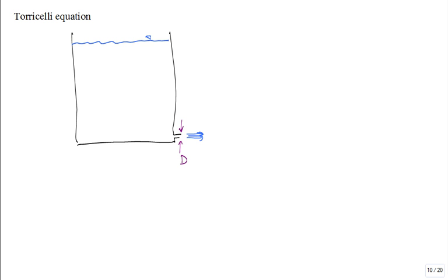somebody says, I think you can calculate the velocity of the fluid coming out of that hole. Can you please calculate the velocity of the fluid exiting that hole? Okay, what I'll do is I'll start right here, and I'll go with a line. That line represents a streamline. If I wait long enough, the fluid packet that started here would slowly go, and finally go out. And so along that line, I have state 1 to start it and state 2 to stop at the end.